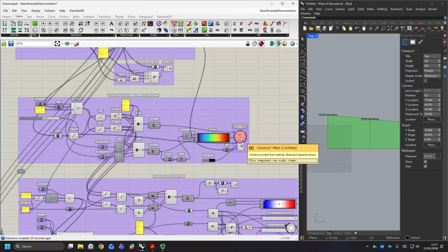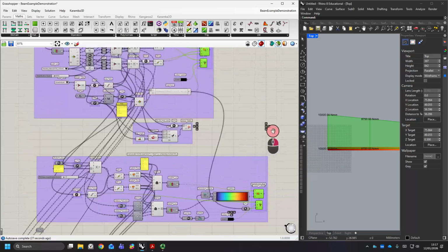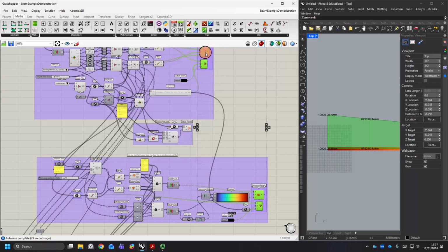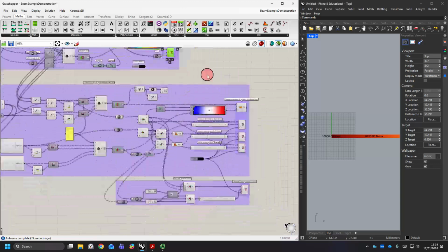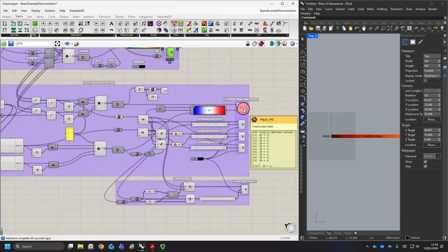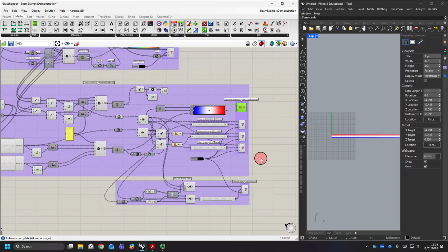Moving on down just to look at the contour plot. So again, that's working as we would expect. I'll just hold control so that we can deselect those. So we have the contour version of that diagram. And then finally, we had obviously through to the stress distribution here and the abs max values like so.